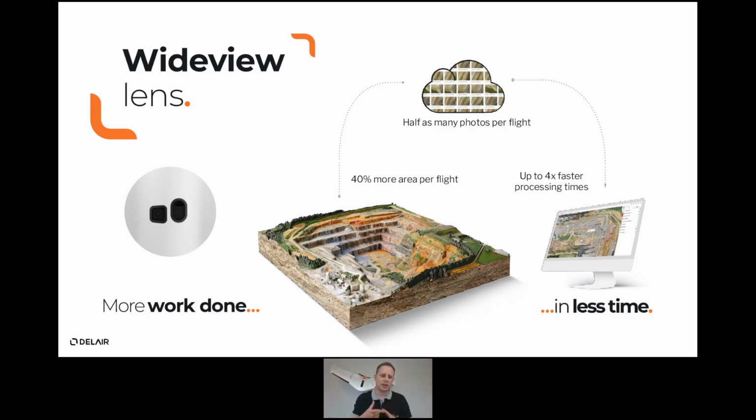It's a good design because it allows you to avoid having any sort of major distortions or vignetting or aberrations, especially around the edges of your image. That just means you're going to get usually more accurate and correct data. You're not going to see a lot of squiggly lines or noise in your point clouds after you do your photogrammetry because of our lens and camera choice. The current configuration I'm speaking about also means you're going to get very high GSD relative to your flight height. So even if you're flying at 400 feet or 120 meters with the current camera on the UX11 and lens, you are getting about 1.7 centimeter GSD.